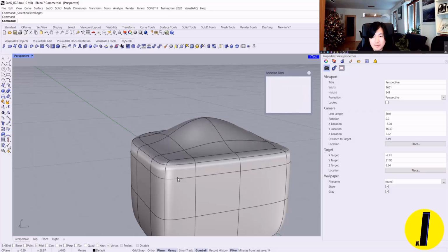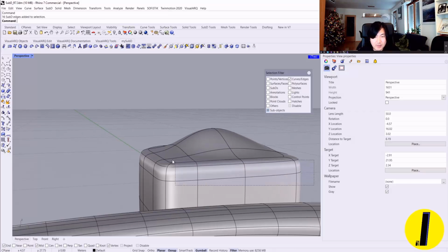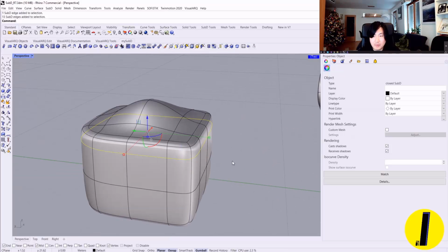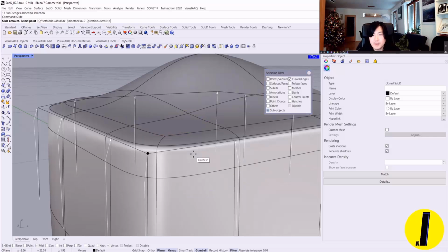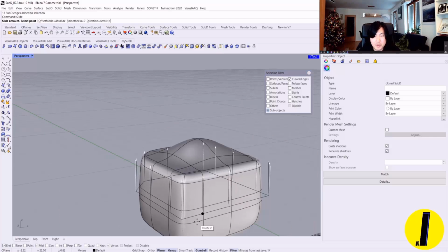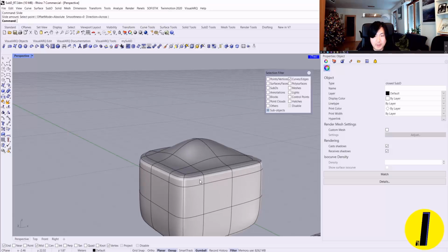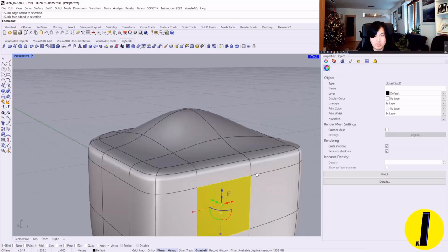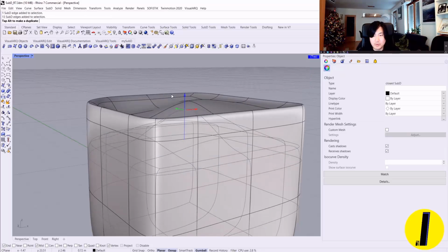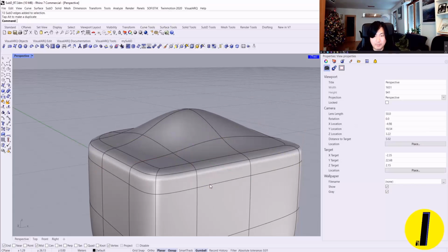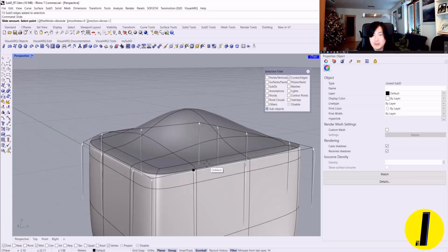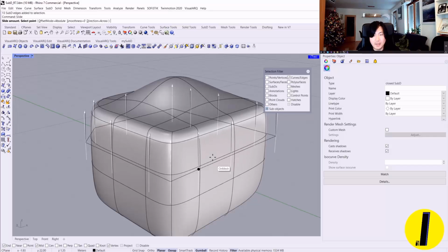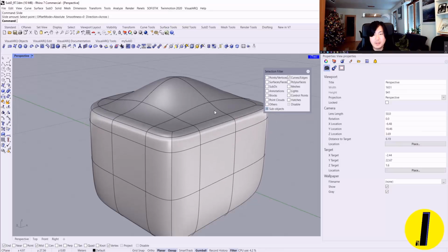So select edge. I'm gonna select these edges here. Sorry, just disable, select, hold this edge loop, and if I type slide, then we can slide this position of the edges. If I move it up, instead of just using the normal move tool, because if you use the normal move tool, then the whole geometry is moving, as you can see. But if I do slide, then we can only slide this edge loop to change the prototype topology.